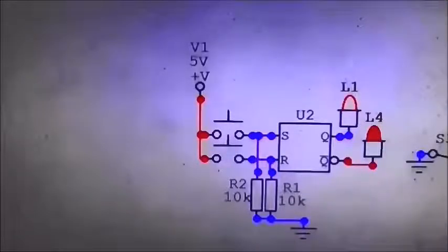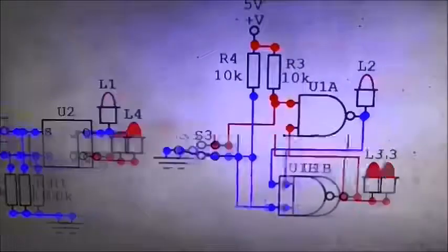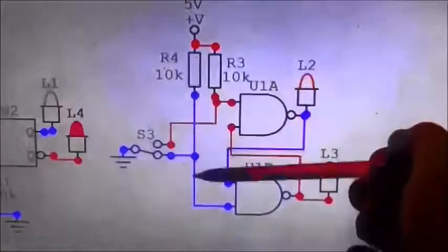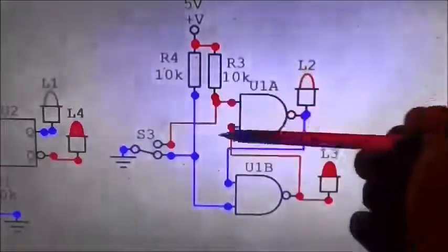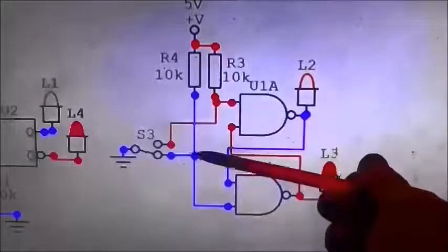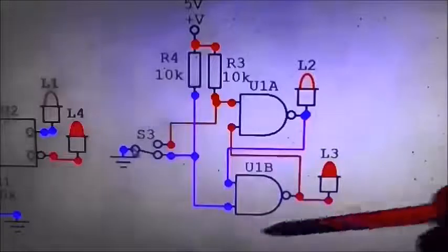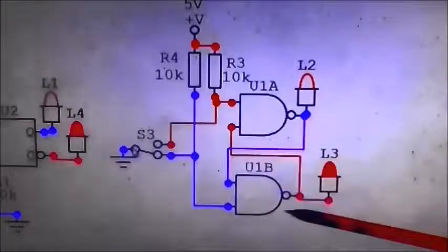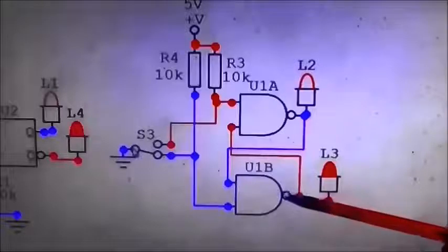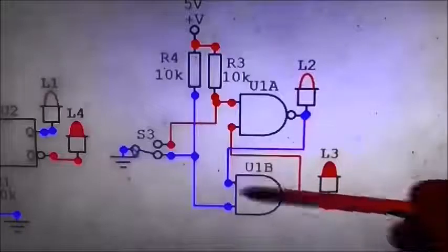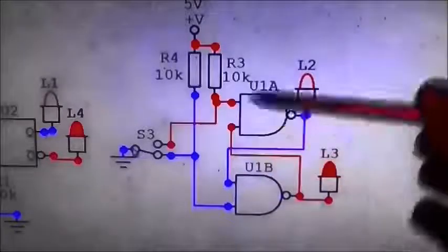And moving along, the idea of the set reset latch is illustrated here. And what we want you to notice is that, again, there's a low level and there's a high level. If I do this, and the idea is illustrated here, and that it's two NAND gates, and basically what we do is we feed back the output from one to the other in both cases.